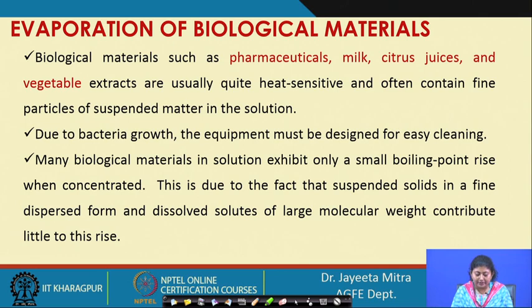So, all this biological material that we are talking about exhibits a small boiling point rise when concentrated, because they have the suspended solids in finely dispersed form or have large molecules that are dissolved. So, they generally provide a very small rise in the boiling point, because their nature is not like a sodium hydroxide solution or NaCl solution.